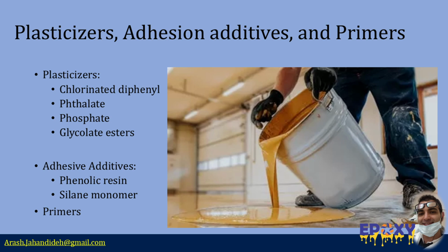Toluene is occasionally used in small amounts to enhance extrusion properties, making the material easier to apply. However, its usage is minimized to reduce VOC emissions and avoid volatility-related issues. Specifically, insulating glass sealants require low volatility plasticizers to prevent fogging within the sealed unit, fogging being a major concern in double glazed systems.